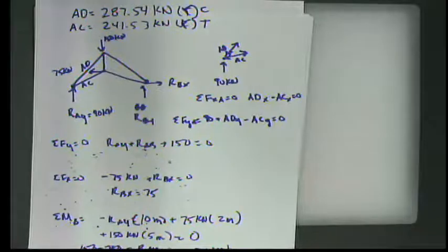Okay, yeah. So when we look at a joint, if a member has a force moving away from that joint, we would say that that member is in tension, because it's pulling on the joint. And if it's pushing into the joint, then it's in compression because it's pushing on the joint. You can think about it, and we're not doing this, but this expands the thought: if you think about the structural member instead of the joint, if it's pushing on both sides, it's going to be in compression. So, very good.